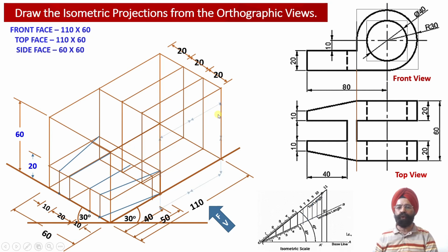We know that when we obtain a square in an isometric projection, it appears like a rhombus, and in this rhombus the midpoints of all the edges have been obtained. And we know the characteristic of the rhombus. If we join the opposite corners, we obtain the minor diagonal and the major diagonal of this rhombus.